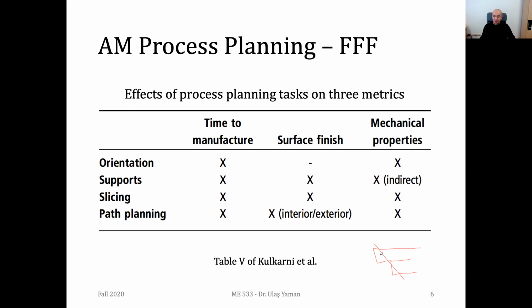Although this was the original plane, once you do the printing, you have a kind of a staircase, and that staircase is visible if you have thicker slices. If you decrease the slicing thickness, you cannot easily see the staircase effect, but in any case, regardless of the thickness of the slice, you will always have some amount of this staircase issue.